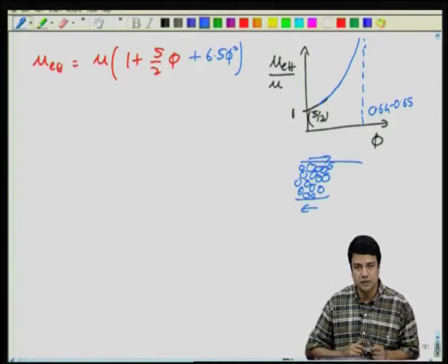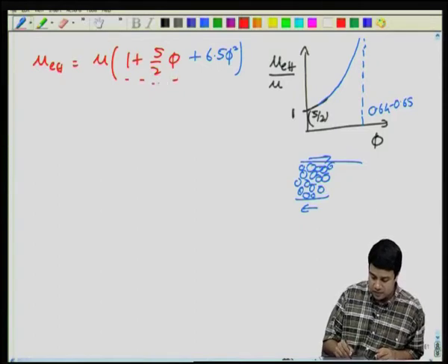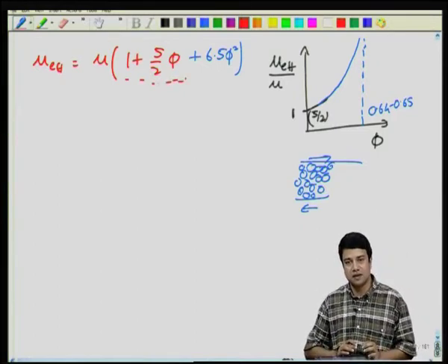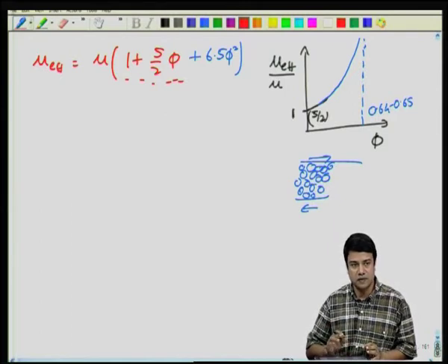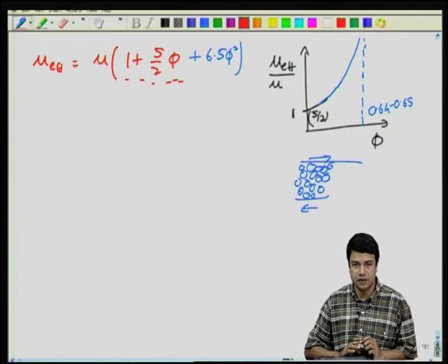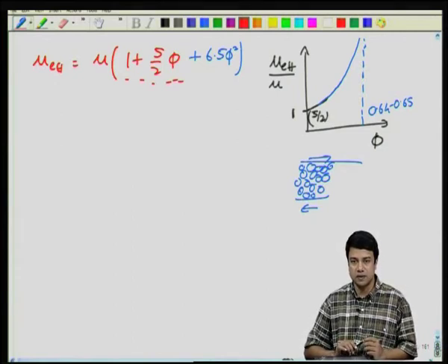In this lecture, we have calculated only this one term for the dilute limit, but you can experimentally determine the viscosity even in the very dense limit, and it will diverge at 64%. So, I hope you found this interesting. This Einstein viscosity is actually quite a significant result, which was evaluated even without many of the techniques we used here. So, it was a pretty formidable calculation.